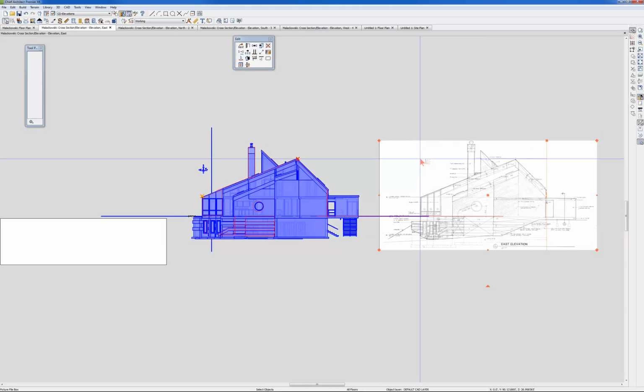So I can use this image and just put my cursor on there. So okay, I know that tells me where that peak of that roof is. I can draw stuff, trace over stuff here and move it over there, which is what this red stuff is, which gives me the general shape. It just makes it very easy to copy these window sizes and stuff if they weren't called out on the plan.